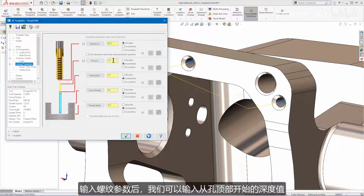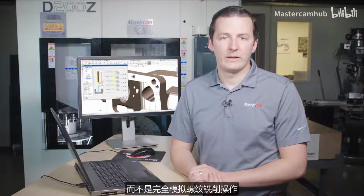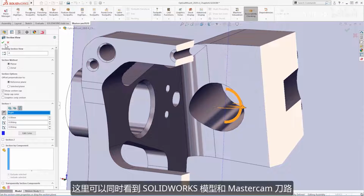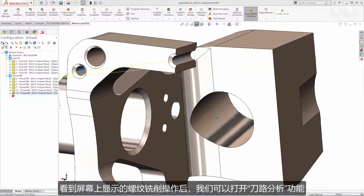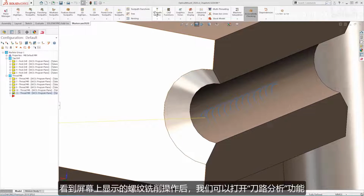After entering the thread parameters, we can enter depth values incremental from the top of the holes. Rather than fully simulating the thread mill operation, we can preview the operation by using SolidWorks Section View functionality. This section is both the SolidWorks model and the Mastercam toolpaths. With the thread milling operation displayed on the screen, we can activate the Analyze Toolpath utility.